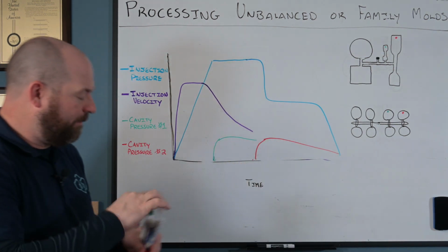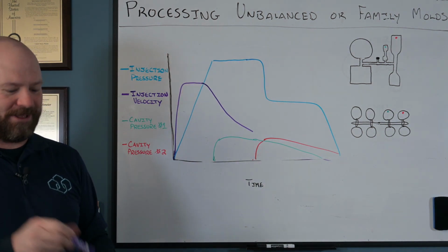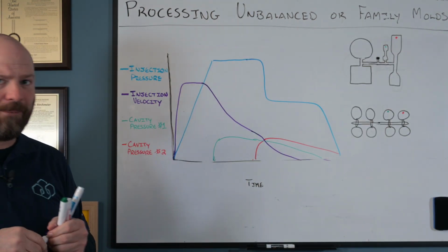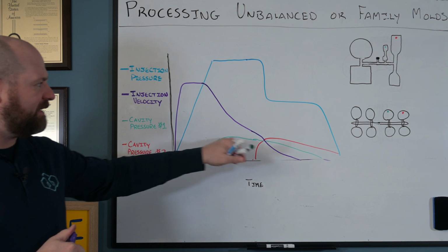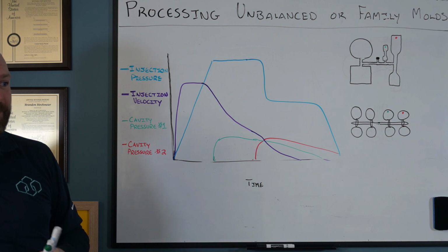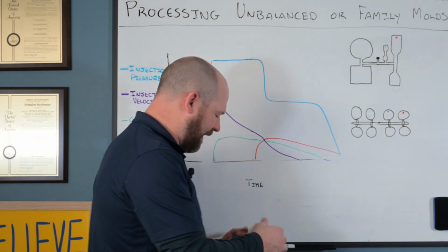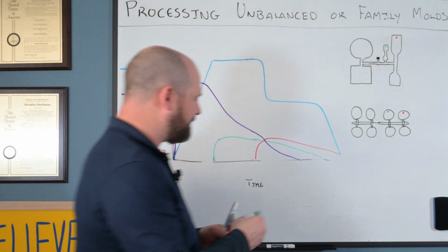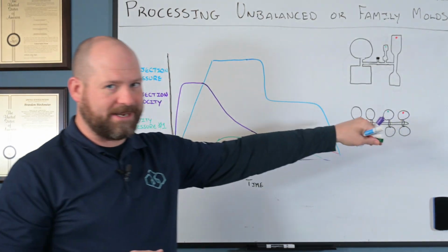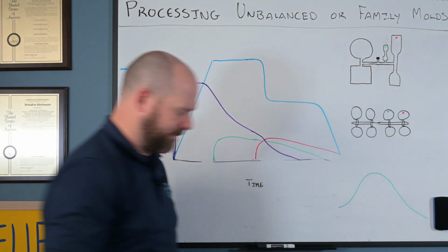What's going to happen in these multi-cavity tools that are imbalanced, especially think hot runner tools, like a 32 cavity hot runner mold that's severely imbalanced, right? What's going to be helpful in this situation is the delta between these parts will narrow. So if you were to fill these parts out completely, your imbalance distribution will narrow. What I mean by that is your normal conventional molding process. If I was to go all the way and transfer when this was at, say, 95% full, my weight distribution may look something like that.